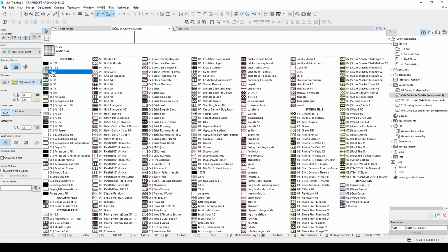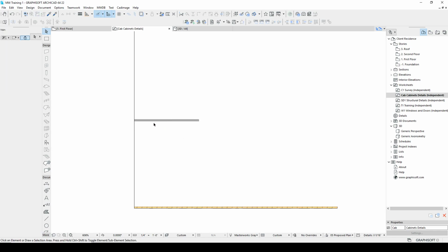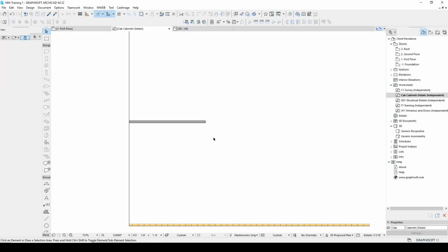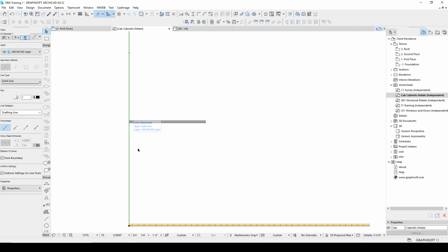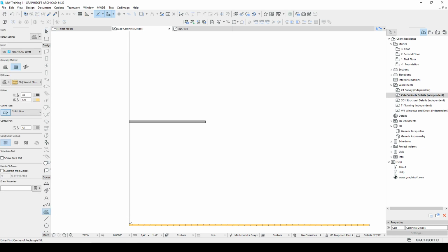Here, I'm going to do a material that's just a 20%, and I'll do sort of a gray color to represent the slab, and I'll put a line around it, and I don't need a real heavy line. I'll do a 0.2, and that's representing my counter. Now I like to set my cabinets a 1/4 inch from the wall.